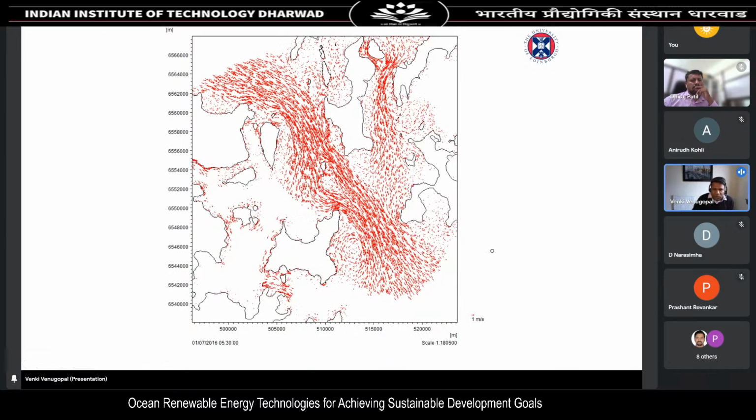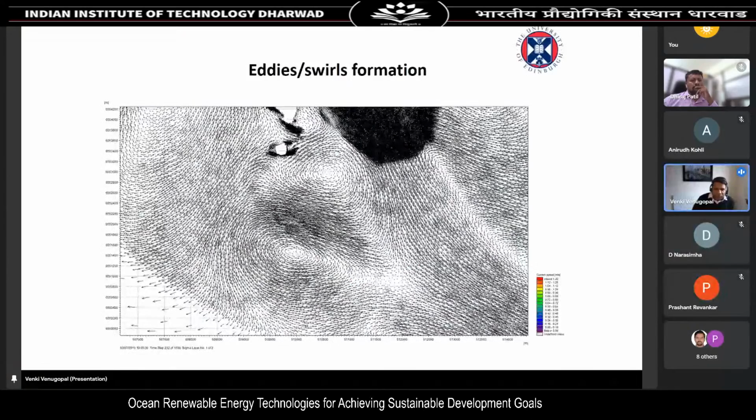This just shows you the turbulence. I want to point out that when you have turbulence produced by wave-current interactions, the turbulence could be like a rotating mass of water. It's a very heavy rotation. So the reason we locate these regions is so that you can avoid these hotspots, because that's where the water mass is very unstable. Therefore, you are going to avoid the regions. It's like a little tornado underwater, so it's better to avoid these regions.